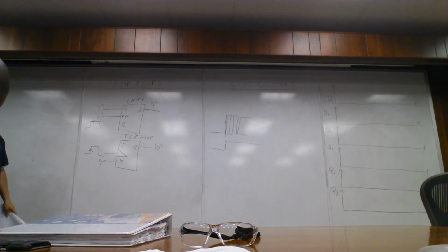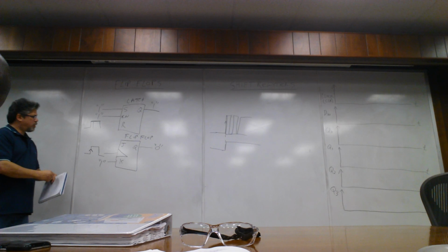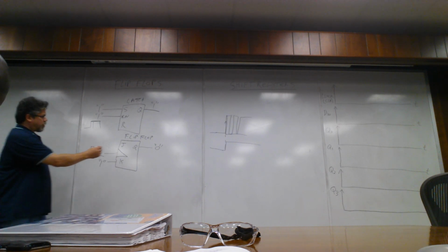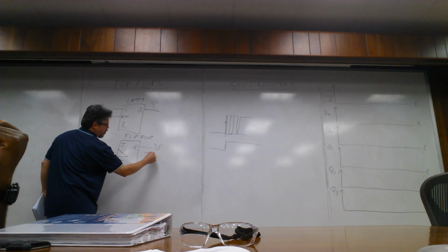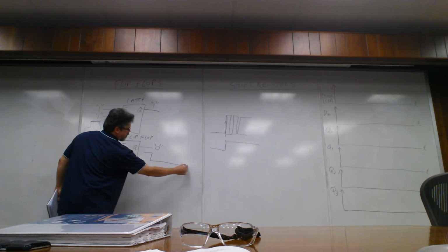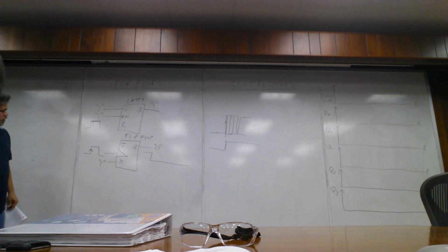Okay, as long as K stays 1, yep, when the next time you have a positive going edge, yep, which would be the beginning of the next cycle, then you would flop, and the Q would now become 1. Right. So this is going to stay 0. If we were high, it's just going to stay 0. It was triggered, and that was it until the next clock cycle. Then it looks at the next pulse.